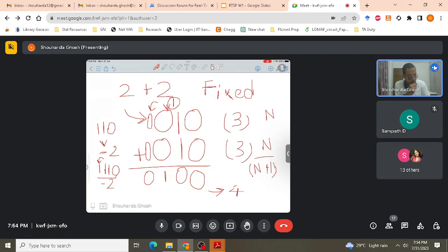Now when you talk about the floating point units in your devices, let's say in your CPU, my laptop is using a 64-bit processor. That 64-bit processor has double precision word length, so it will have some bits of mantissa and some bits of exponent. The mantissa and exponent calculations also have to be manipulated, and they have their own circuitry. The simple thing is that the circuitry for floating point is extensively bigger and has a higher number of units compared to fixed point.